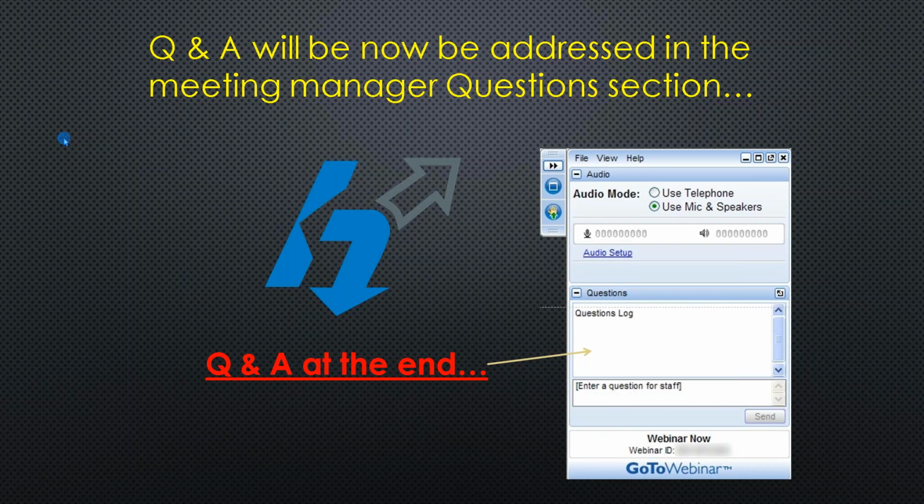So it's usually easiest to chart your results, and you're going to see that outlier real quick. Chart not just the results, but what your settings were during that test. What was your global mesh, and were you using any local mesh control? Because that's really all that's changing. You're not changing your load, your materials, your boundary conditions or your constraints, just refining that mesh. So you only have 2 or 3 pieces of information to chart.